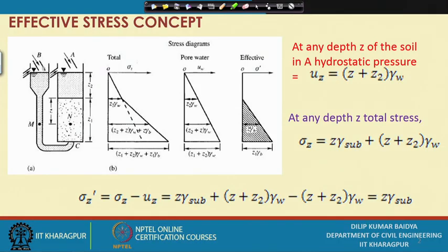That way also one can find out. So, this is actually the no flow condition, that is the static case. In fact, whatever I have discussed in the previous lecture is almost similar. Only thing I have shown is that if this tank is elevated slightly to this side, the tank height is raised here and the overflow is kept here, that means the head is here. At this point hydrostatic pressure is more, at this point hydrostatic pressure is less. So, because of this head change, the whole flow will take place in this direction.